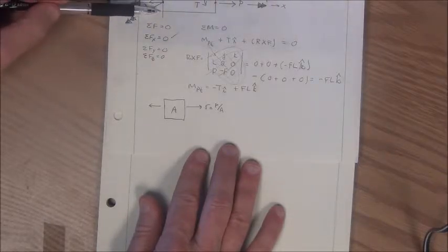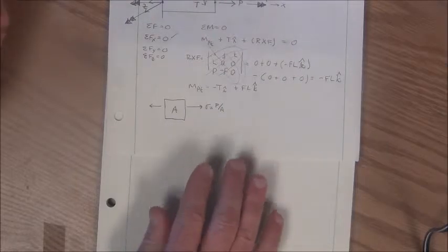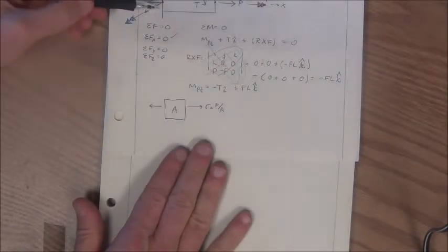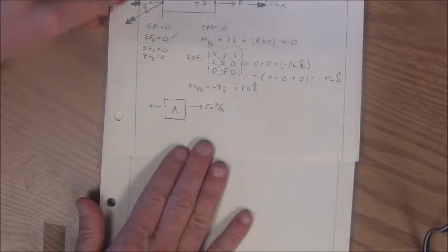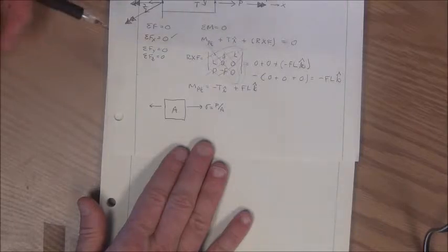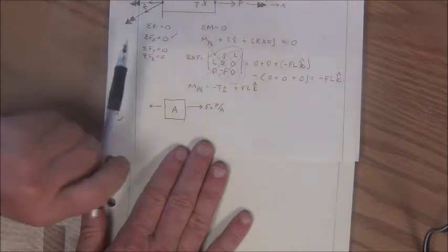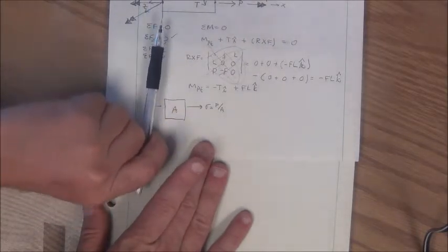It's a shear acting in the plane. But I need to remember the stress profile for the shear. And I need to remember that for a transverse shear, where the shear force passes in that plane, Q will be equal to 0, and I will be looking at a stress-free surface. And so force F will not do VQ over IT because that arrow would pierce right through